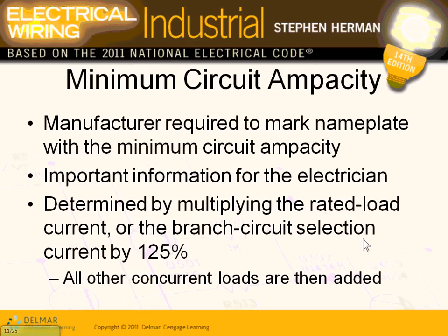Okay, minimum circuit ampacity. We talked about this one, guys. This is where you're going to size your conductors. That's a done deal. If you don't have this value, if you don't have the minimum circuit ampacity, then you have to treat it like any other motor.